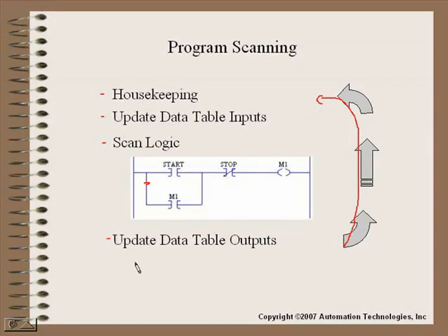This is called PLC program scan, and a PLC program will scan repetitively as it's running and constantly updates its outputs, constantly checks its inputs, and that's the important thing to remember about programming in a PLC. PLC program scans are very quick. You will see them on the order of milliseconds and microseconds. So we're looking at information that's being processed very quickly, and obviously has to be able to monitor relays and to be able to monitor encoders and other fast-acting devices out in the field.